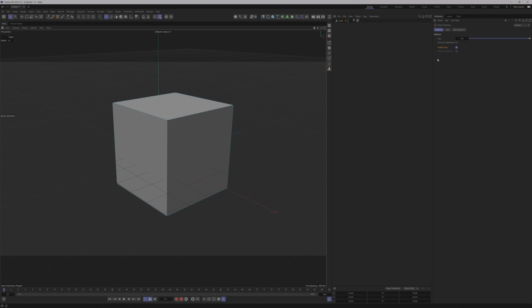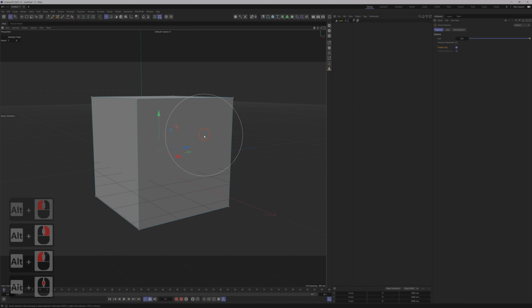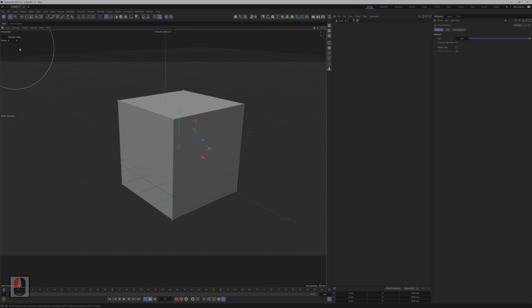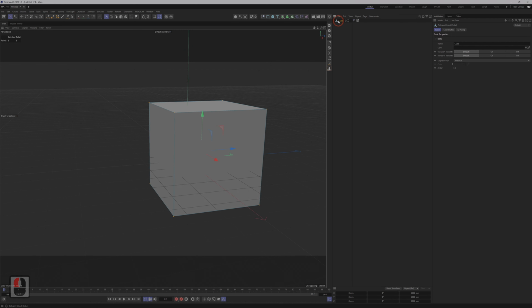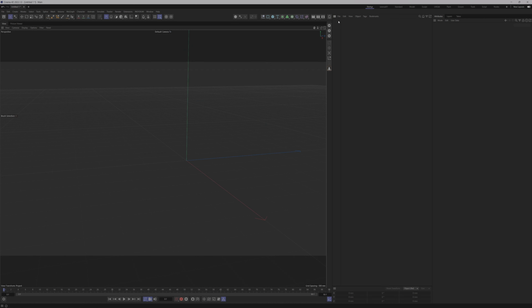When visible only is on, you try to select everything from this view, you only select 7 because you're not selecting the one in the back. This one. But you unselect everything and go Alt tilde. Visible only is off. Now I try to select everything from this view. Everything's selected, 8 out of 8, because this toggle's off. You'll be using this a lot. I use it a lot when I also have some other shortcuts, but I think I'll be showing you those as we actually use that.